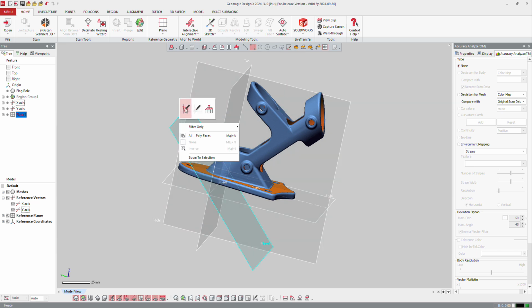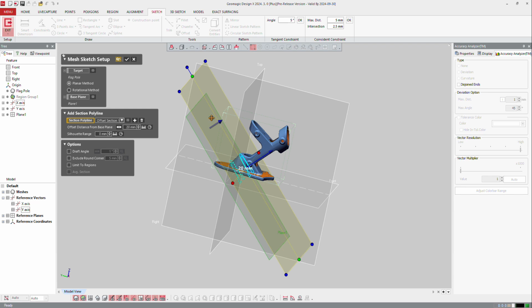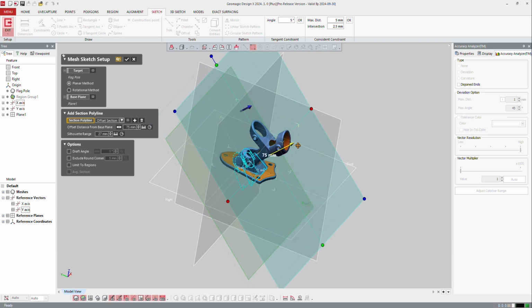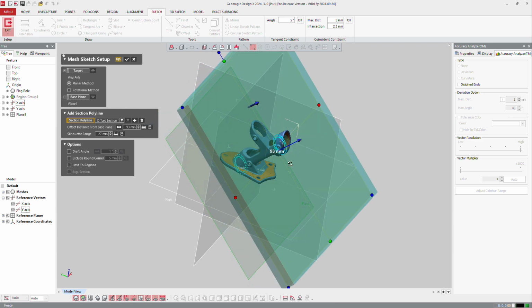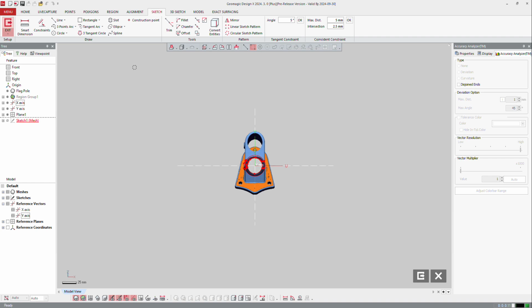I will make a sketch here on the part and move it up just to get the global shape of that part. If you want, you can ask for silhouette, but I don't want to get that outside, so I will move it up, to get the cylinder here. And okay. From that point of view, I will create, based on that center, a center rectangle.